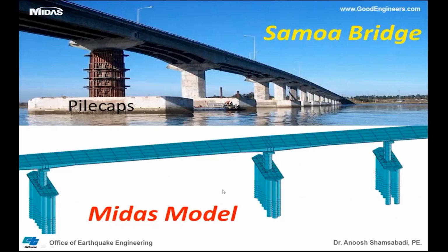Now, the pile caps are very massive. This is actually part of the retrofit that we were doing. The retrofit actually was done in early 2000. Here is a pile cap which is very massive with the pile foundation. For this type of a structure, the modeling of the pile cap, correct modeling, correct dimension, correct mass of the pile cap is extremely important because it's a dynamic system and mass comes into play. So it is very important to make sure you include the pile cap mass and, if you can, the pile foundation as part of your global system. So all the mass participation will come as real as possible.